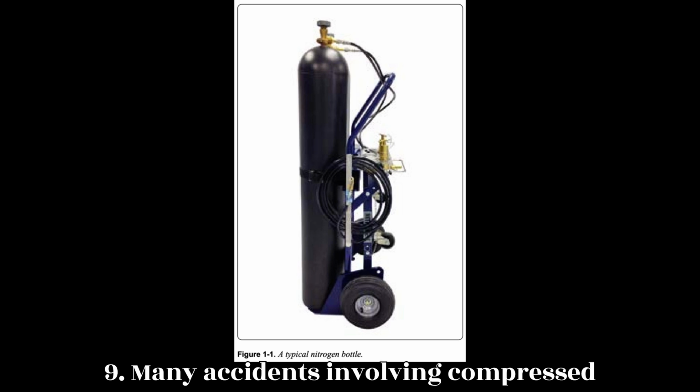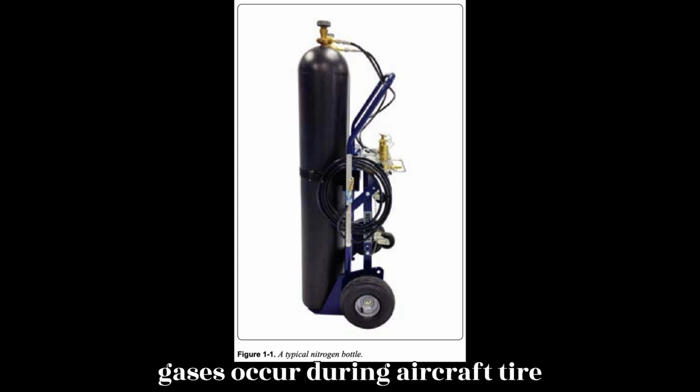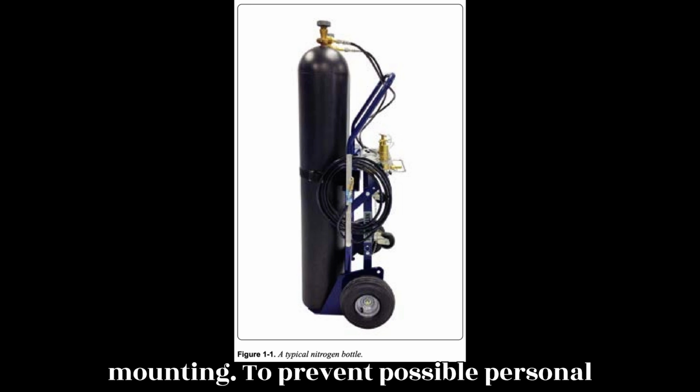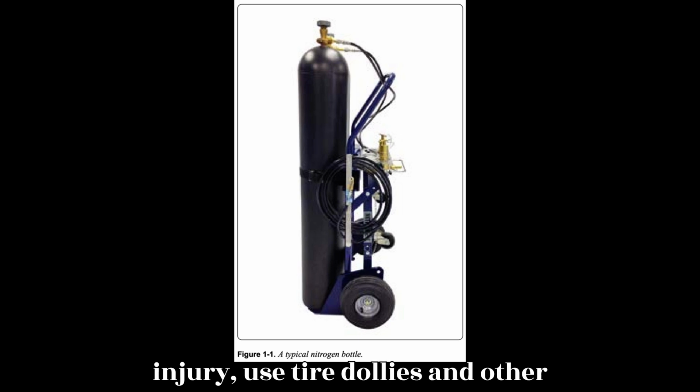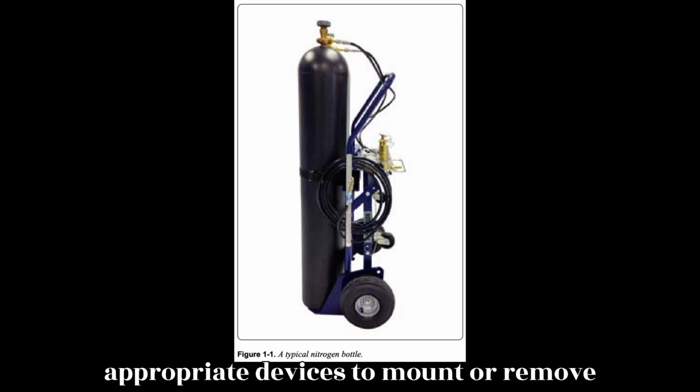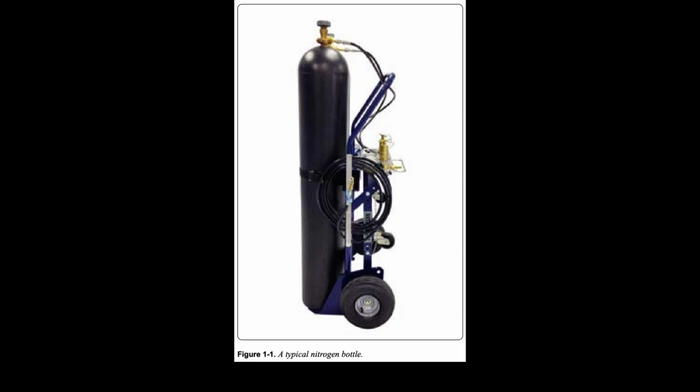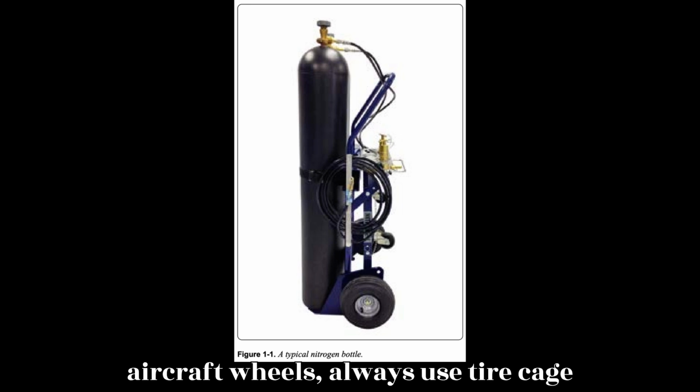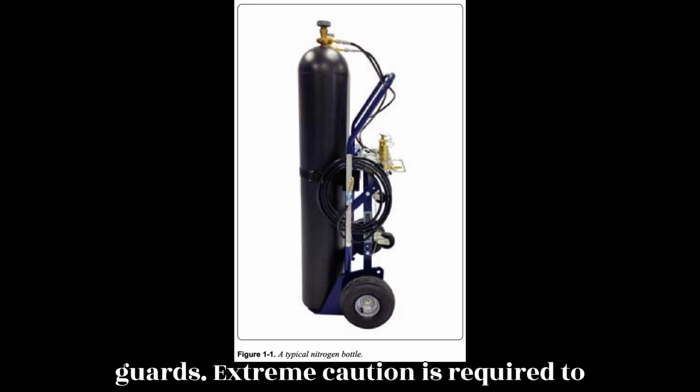9. Many accidents involving compressed gases occur during aircraft tire mounting. To prevent possible personal injury, use tire dollies and other appropriate devices to mount or remove heavy aircraft tires. When inflating tires on any type of aircraft wheels, always use tire cage guards.